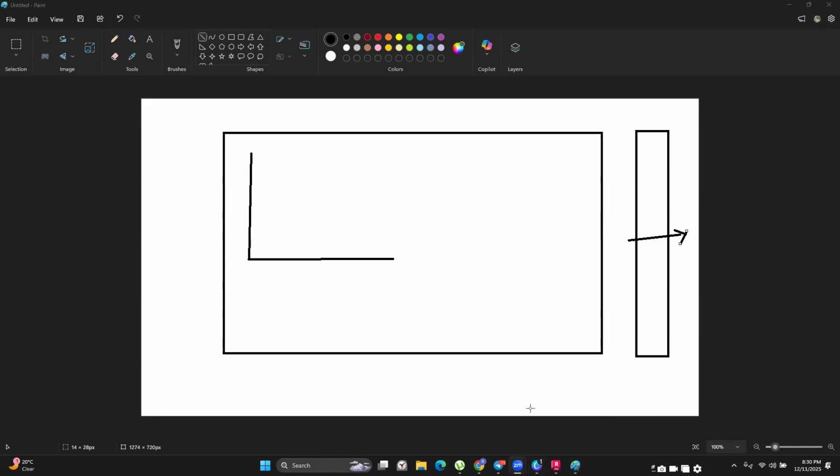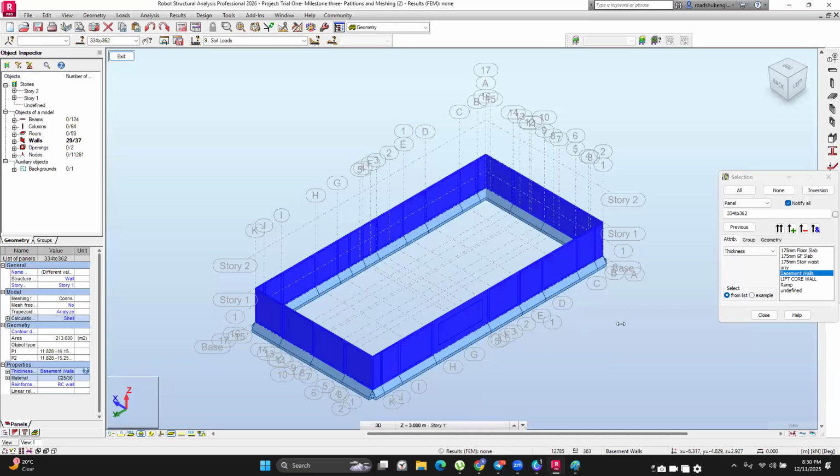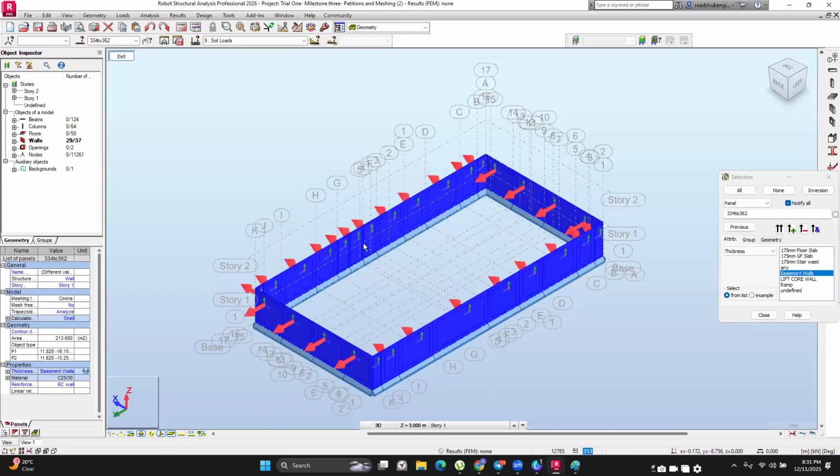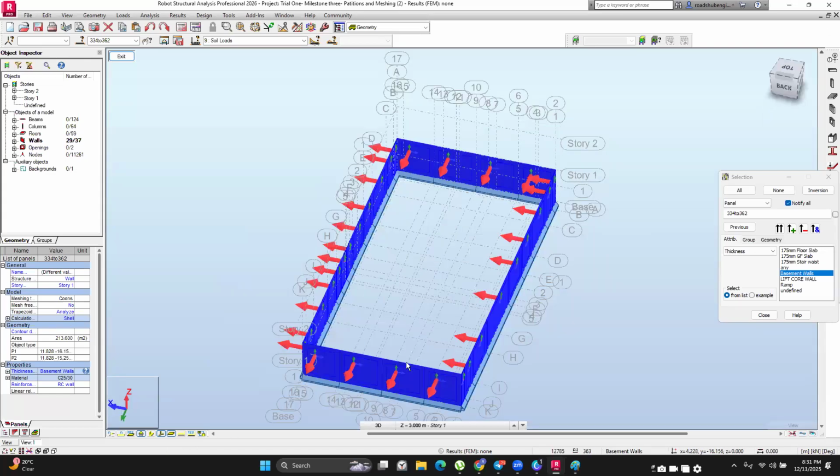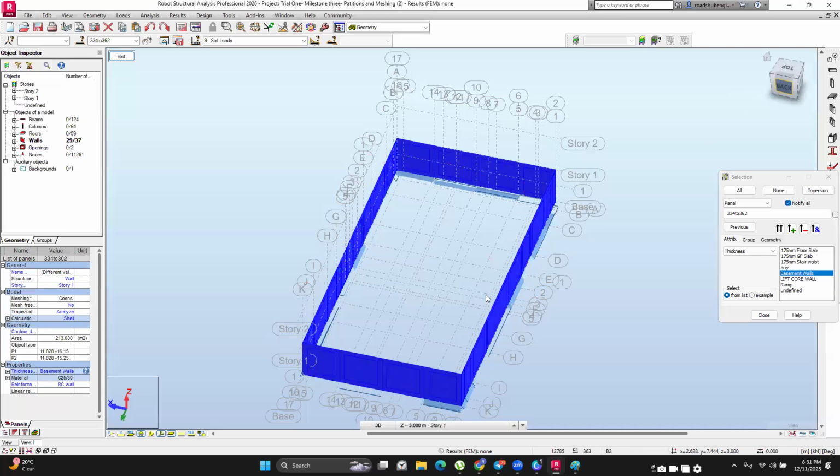Okay, so I'll proceed, I can see we are good. Now from there, we can define the soil loads because their application is dependent on the local axis. To view the local axis, you just go to these options just below the global axis. Once you click on these options, you have the local systems. Click on them once and you can see the local systems, and you can see the axes we've been talking about.